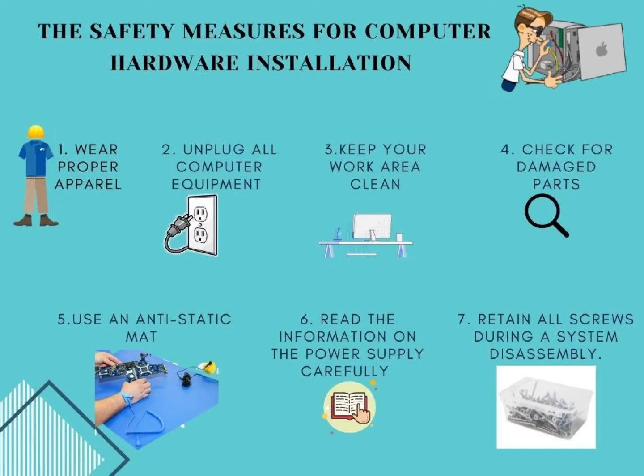Here are the safety measures before we start the installation of computer hardware. First, wear proper apparel. Second, please unplug all computer equipment. And third, please keep your work area clean. Next, check for damaged parts, if any, and use an anti-static mat. Before that, you must read the information on the power supply carefully, and the last is retain all screws during a system disassembly.